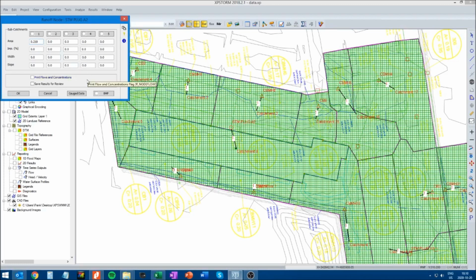So that is okay. So we're gonna start populating these tables, and we have one subcatchment per node, or the other way around. We have, for each node that's receiving runoff, only one subcatchment. So we'll put in the imperviousness. So for this one, I know it's 100% impervious because it's a building roof, so we'll put 100.